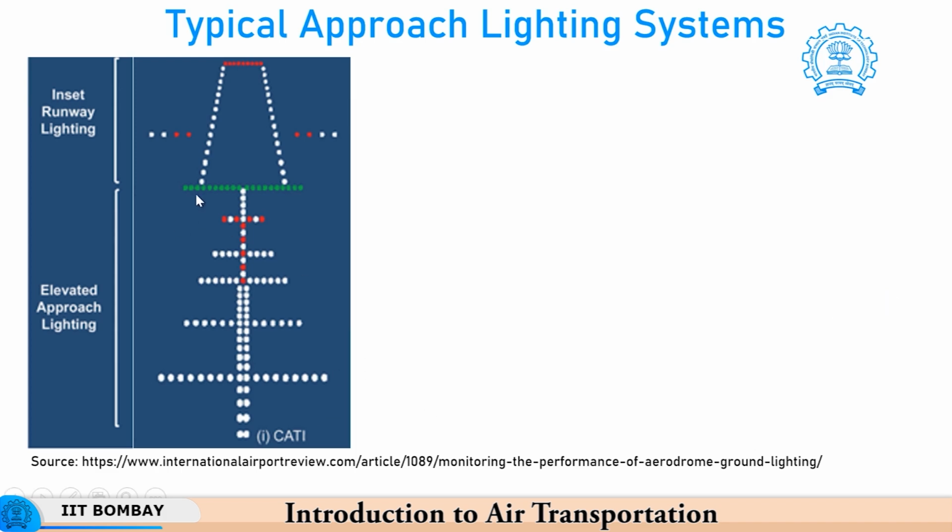The ones below the green line are beyond the runway touchdown target point, at some elevation, and what you see above it in this figure is the runway. On the left and the right hand side, you can see there are 4 lights each, and this constitutes what is called the precision approach path indicator, abbreviated as the PAPI lighting system.